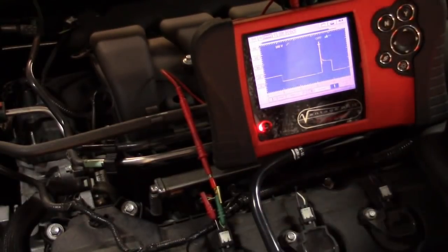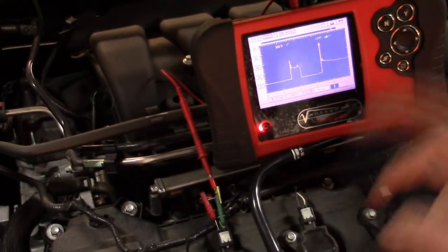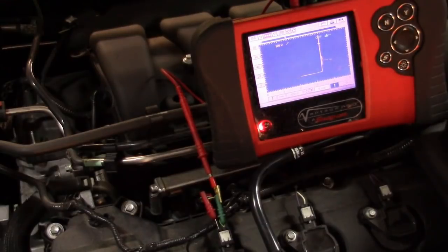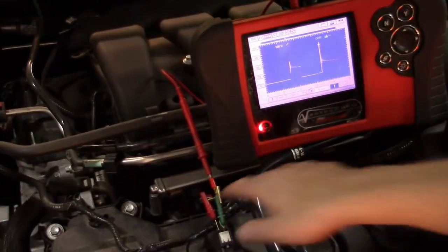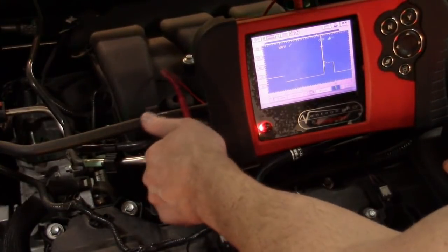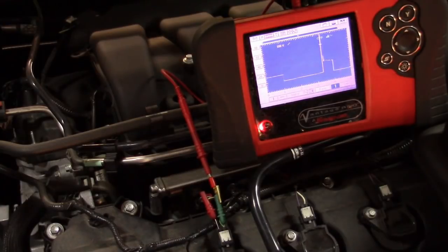So what does this show? Just what I said. This phenomenon that the voltage spike is only happening on the ground side of the coil, okay, after the coil. That's where our counter-electric force phenomenon that we discussed, and you guys fully understand, is taking effect. It's not on the positive side of the coil, it's on the ground side of the coil. This is my positive lead on the ground. Okay, you guys understand that, I know, all right?